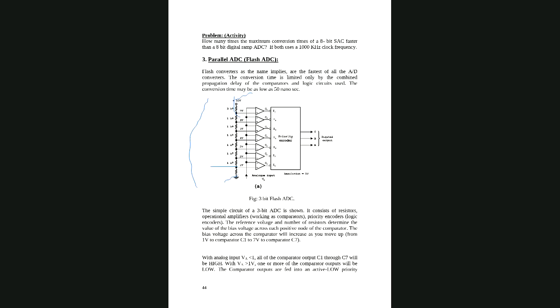Clear, everybody? So at this point I get 1 volt. What about this next point? From here to here, it will see how many resistors? 2 resistors, right? So we have 2 kilo over 10 kilo times the total voltage of 10 volt. So how much did I get? 2 volt. Is it okay, guys? Is it clear? Everyone okay?